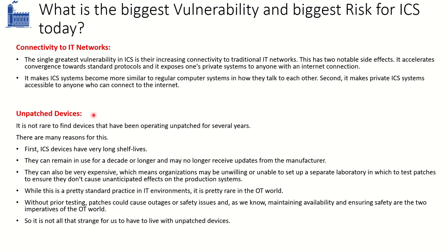And in an IT environment, you get this flexibility of downtime and testing the patches. Building a test environment for testing patches in an IT environment is not very costly. You can take a few systems, build a test lab, test the patches there, and then regularly deploy them to the production systems. Plus, you have this flexibility of taking regular downtimes. But in an industrial environment, you do not have this flexibility of taking the downtime.